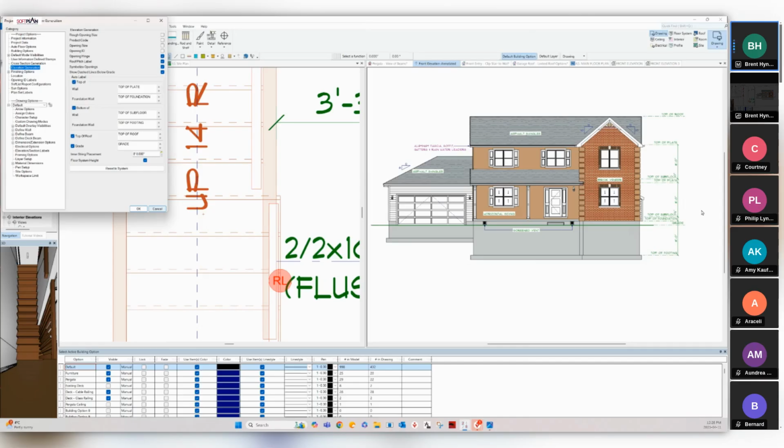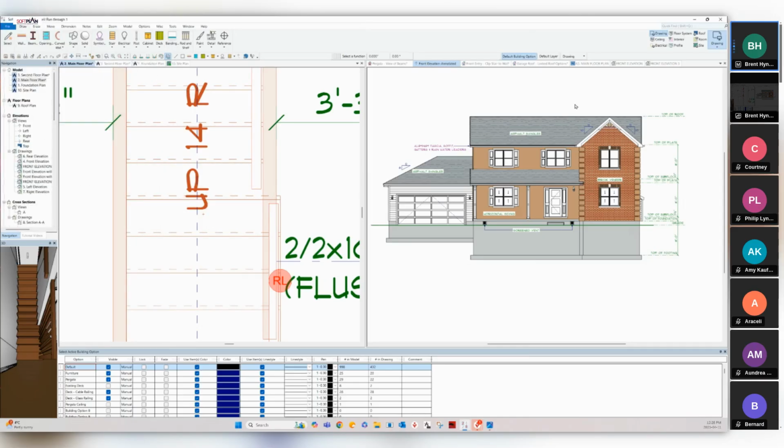So I'm just going to close that out. We have the setting we want. If I look at my model stack, I have a site plan included in the model stack. So if there's one there, that's what we're going to use. If that is 8 inches down from the top of the foundation, that's where it's going to transition from a solid line to a dash line.